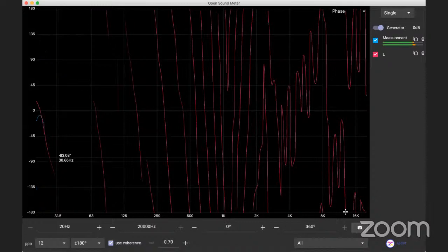A 100 SPL A-weighted sound will basically read slightly softer. I mean, you'll get a lower SPL value on your meter, because the A-weighted filter is not going to compute that 100 hertz as much. It is going to try to negate it depending upon the slope rate. But with C-weighting the 100 hertz will seem louder on the reading. So if you play a 100 hertz wave, and you measure it and put that measurement in A-weighted, you'll feel it is soft.